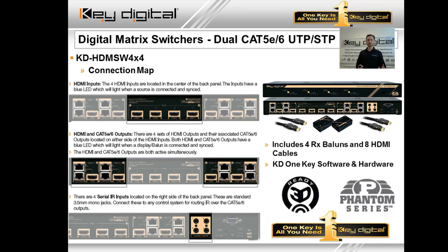One limitation that I didn't mention there, distance. The Phantom series HDMI matrix switchers with the included receive baluns support 1080p at 75 feet, 1080i, 720p, 1080p 24 at 100 feet. So as you recall from some of the balun discussions that we had in level 1, our basic dual cat baluns are about 140, 280. This one is limited to 75, 100. Hey, you need to go those distances and you're still looking for a cost-effective solution. That's not to say this is not the piece for you.